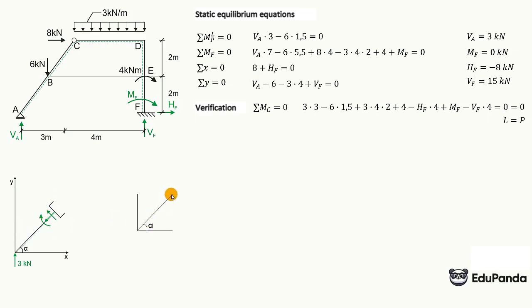Here we have the direction of the bar. Between the direction of the bar and the horizontal, I marked the angle alpha. That is in this place. And I also marked the vertical. And now if I extend the direction of the bar, extend the vertical and horizontal, and drop a perpendicular to this direction of the bar, something like this will form. And here this direction I am now showing is the normal direction to the bar, meaning tensile and compressive forces. While perpendicular to it is the shearing direction, where there will be shearing forces.